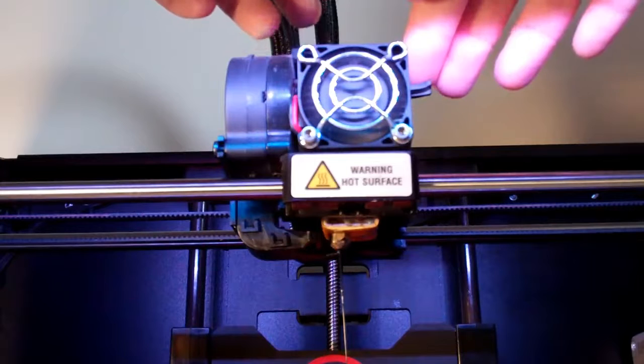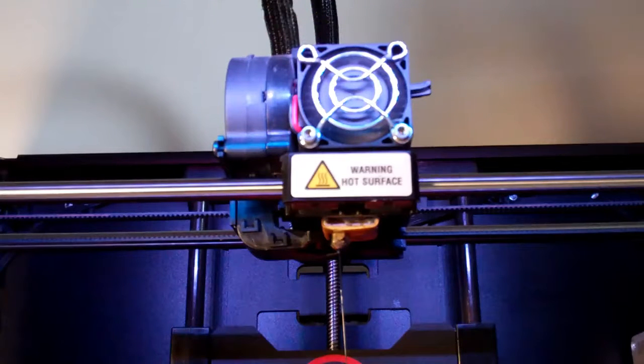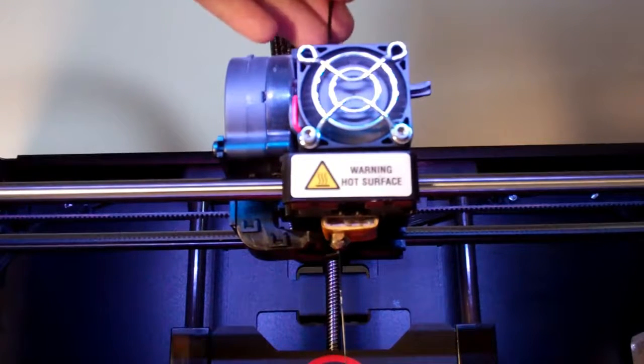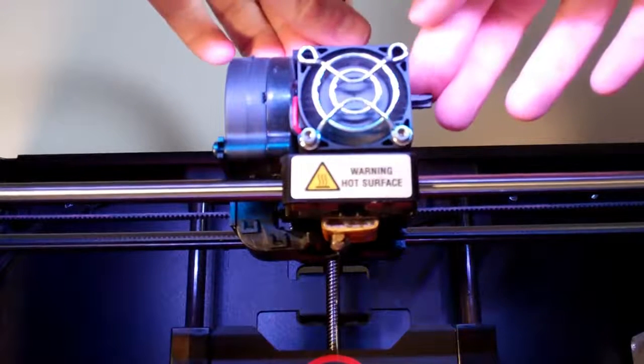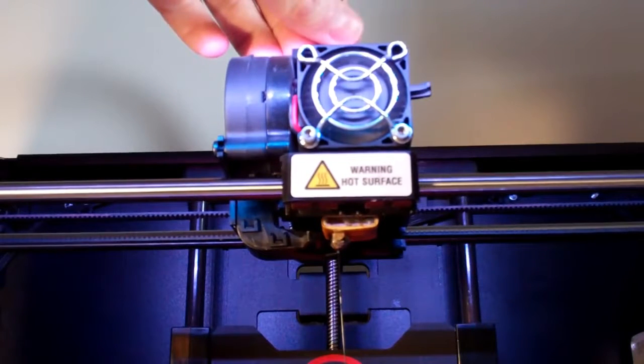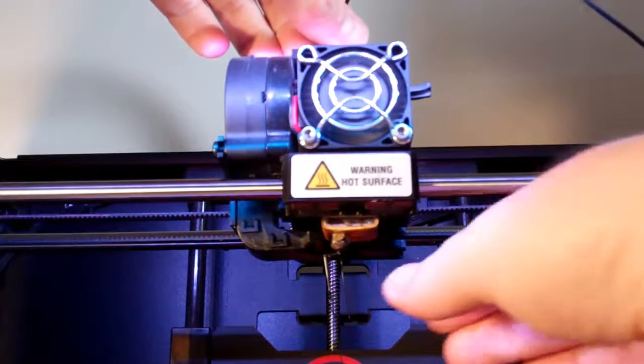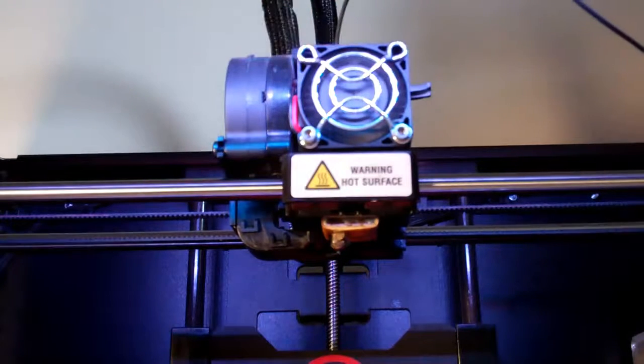We are at around 230 to 240 degrees Celsius at the moment at that hot end, so yeah, it will burn you. So be very careful of that, obviously. So we've extruded some more ninjaflex, took the ninjaflex out, loaded it back in. So now we've done this a couple of times, hopefully all the blue PLA plastic has been removed from the nozzle and it's quite clear. So that's extruding much faster now. You can see the black ninjaflex extruding a lot faster there.